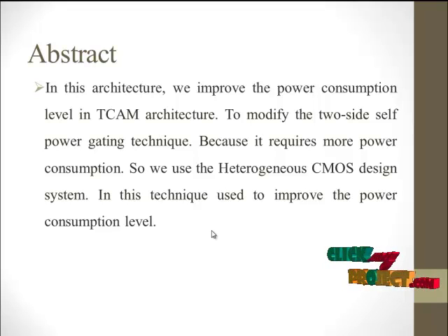With the vigorous advancement of the Internet, the cloud service, Internet of Things, that is IoT, and IPv6 are widely used in daily life. The router is asked for a fast lookup of the packet delivering path. Content addressable memory, that is CAM, is a high performance search engine. Unlike random access memory, which accesses data based on its address, CAM accesses data based on its contents. A CAM compares incoming data with all the words in parallel and returns the address of the best match.